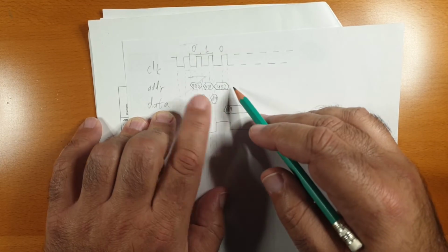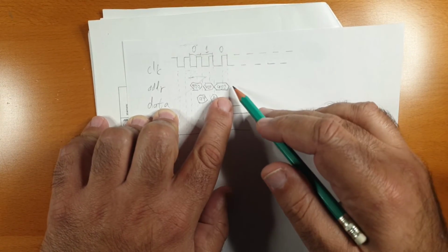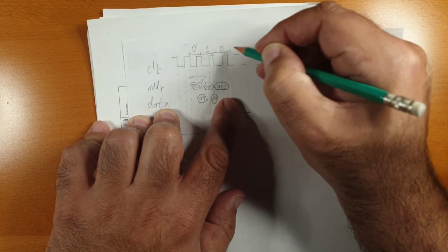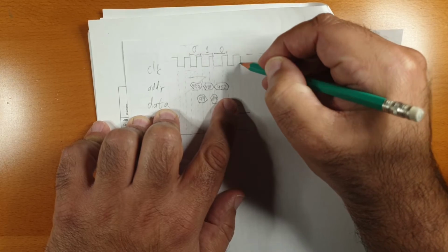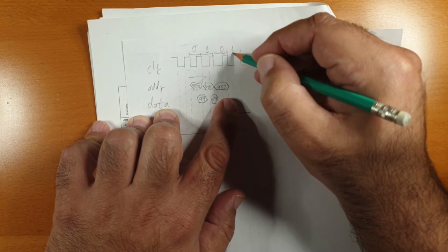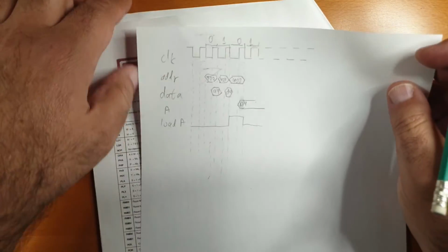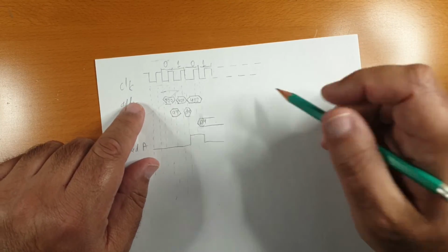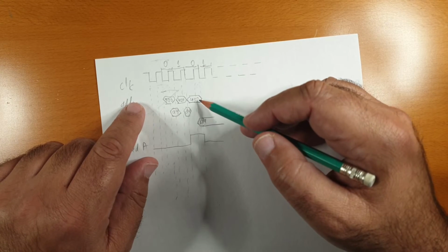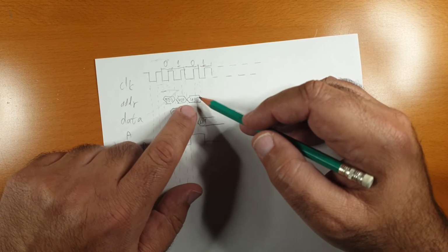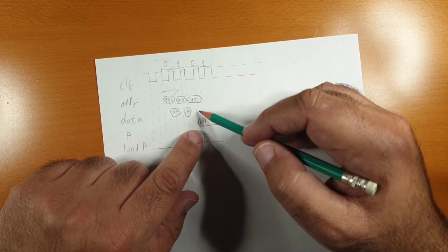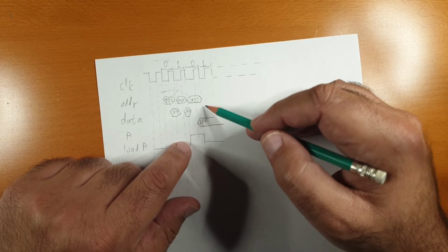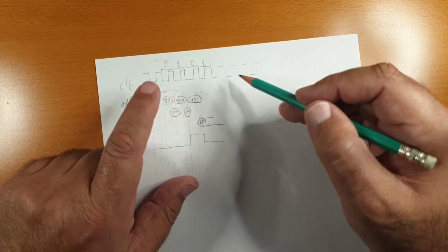On each cycle, we need to advance the program counter. Do we need to advance the program counter again for cycle 1 of the next command? You'd expect the answer to be, it depends what the opcode is. But if you think about it for a second, it actually doesn't. Address 402 will contain the opcode for the next command. But whatever it is, we're done. We've read it, we've parsed it, we don't need it anymore.